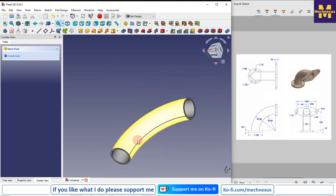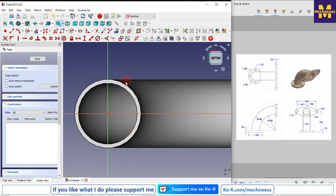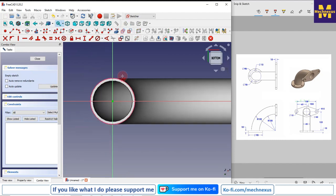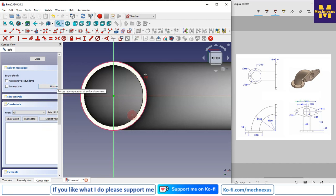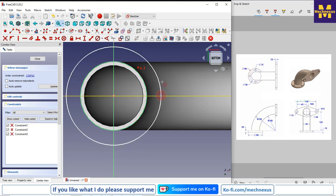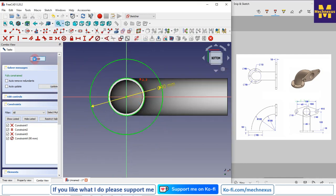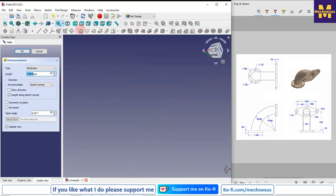I will select the bottom face, and simply I will create a sketch, and now I will project the outer edge, and I will draw the circle, and I will make it equal, and OD of the bottom flange is 90, so I will select one more circle, and I will give it a diameter of 90, and I will close it, and I will go with the pad.